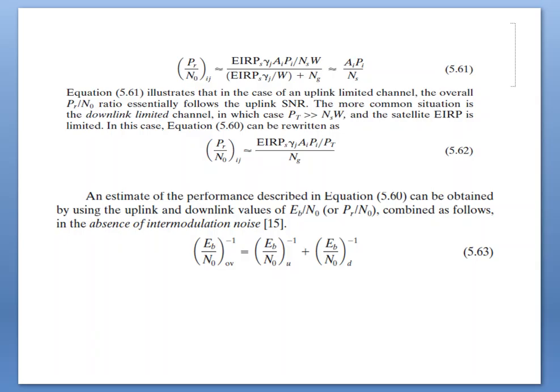The above example represents the case where the satellite transponder is servicing 10 simultaneous users. In this example, all users transmit at the same power level, and each signal is allocated 9.8% of the downlink EIRP.